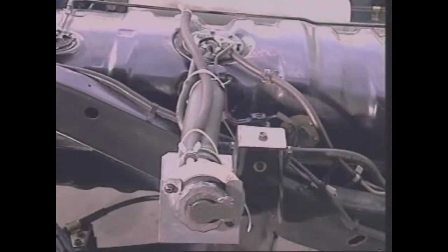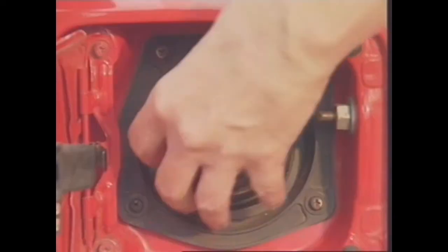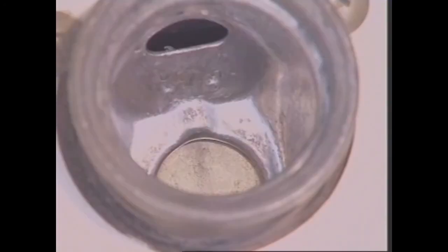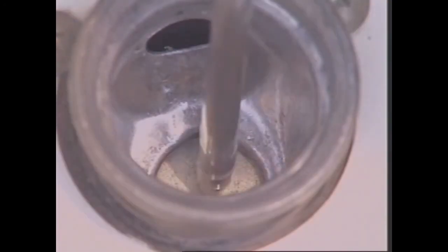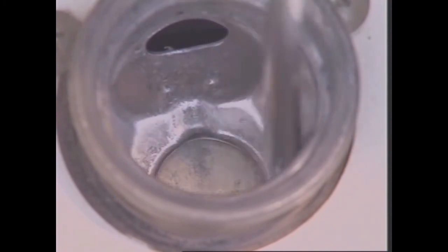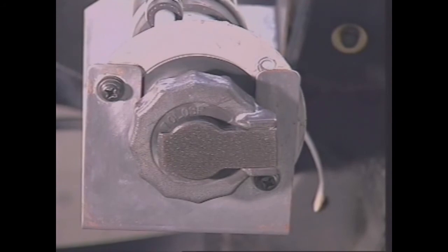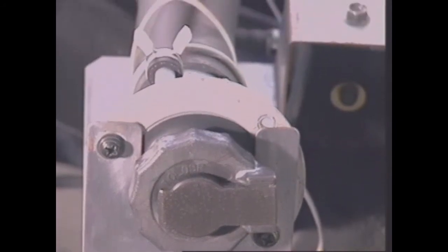The fuel filler is where fuel enters the system. The filler neck is a pipe that extends above the fuel tank. On unleaded petrol vehicles with catalytic converters, the filler neck is designed to prevent leaded fuel being added. Its diameter is smaller than those on leaded vehicles, and a trapdoor inside the filler can only be opened by the nozzle of the unleaded petrol spout. The filler cap seals the filler neck to keep out water and foreign objects.